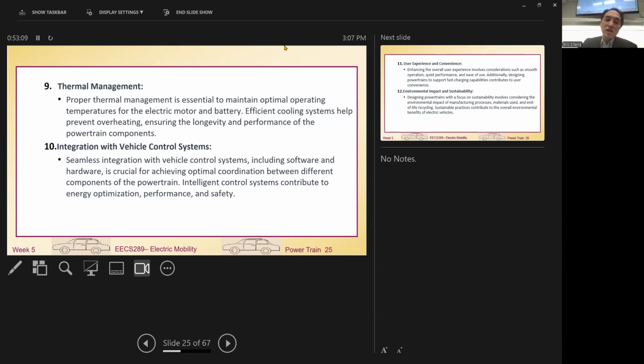And then we also need to think about the integration of the vehicle control unit. Each component in the vehicle has IoT for the information. They also have a connection to the VCU so that all the data can communicate. Today, we do have a standard for each vehicle component. They are compatible with your own vehicle VCU, so they communicate over the CAN bus. But the thing is, CAN is not universally regulated. Each EV company has its own prototype for its CAN.